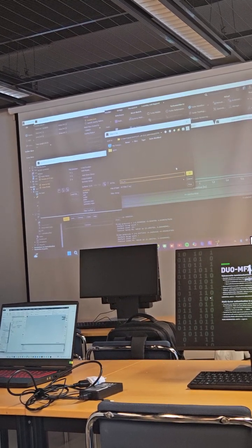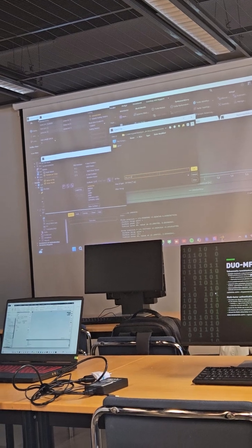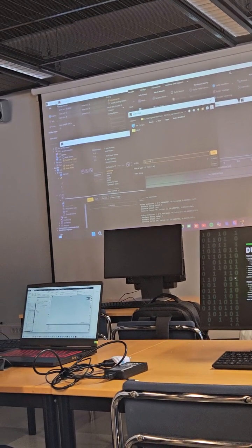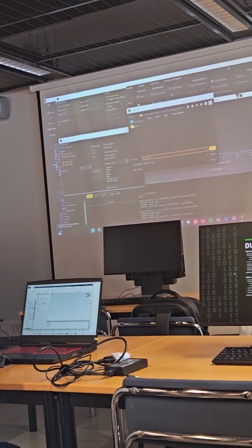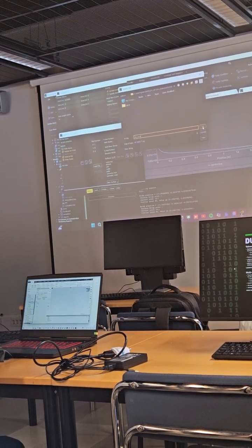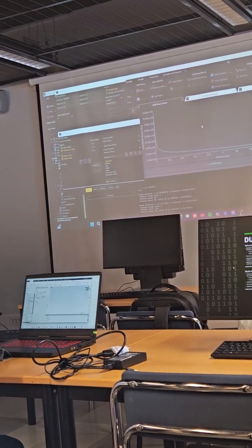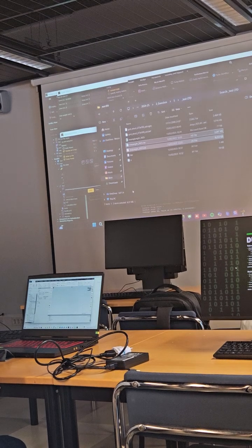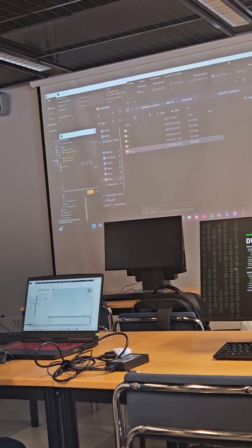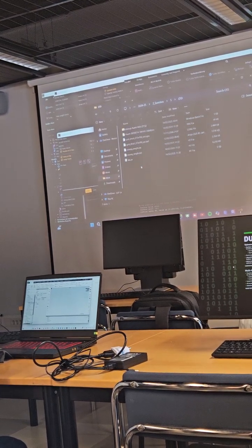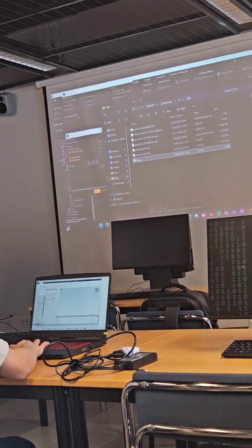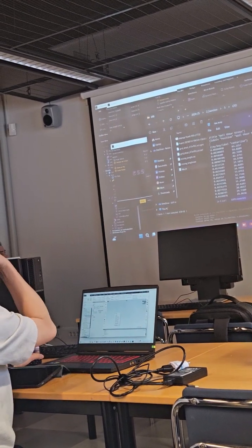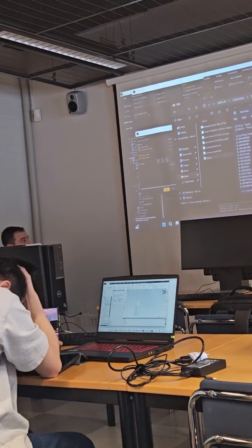And you also need to add .xy, this is the format, and you need to insert it here, .xy. Okay, so now in my working folder I'll have an XY file that you can open like a text file, where you have the distribution of the wall shear stress.